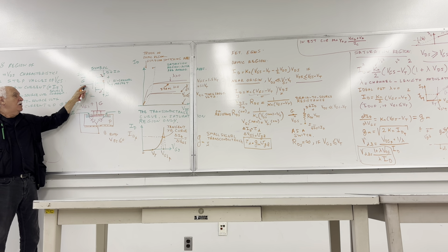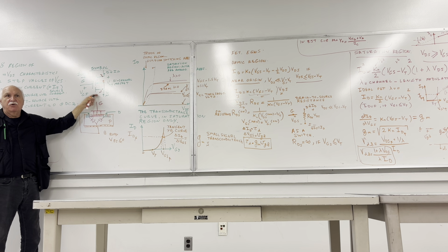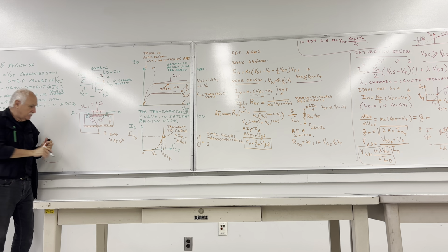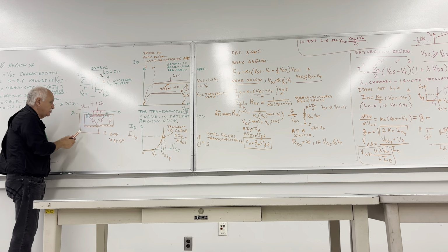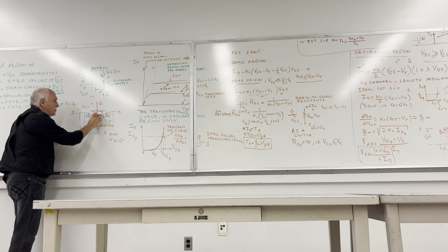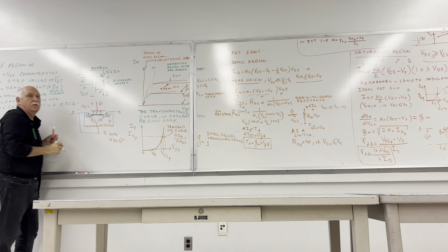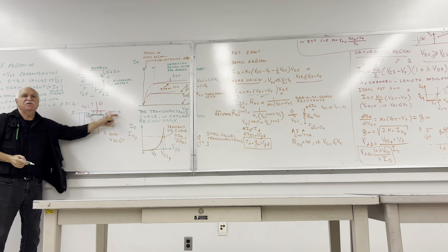Therefore, when the gate to source voltage was 0, in that case, if you had this layer built into the MOSFET, in here, a pre-built thin N layer, no problem for the conductivity.